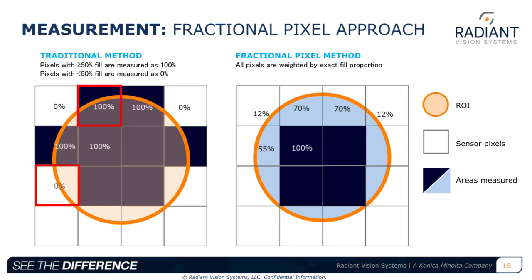The signal of each sensor pixel is weighted by the area of the image sensor pixel within the ROI. This signal is then summed up to determine the overall luminance value of the ROI. In this instance, we get a very accurate determination of the luminance within this display pixel and have much less contributions of potential crosstalk with neighboring pixels.